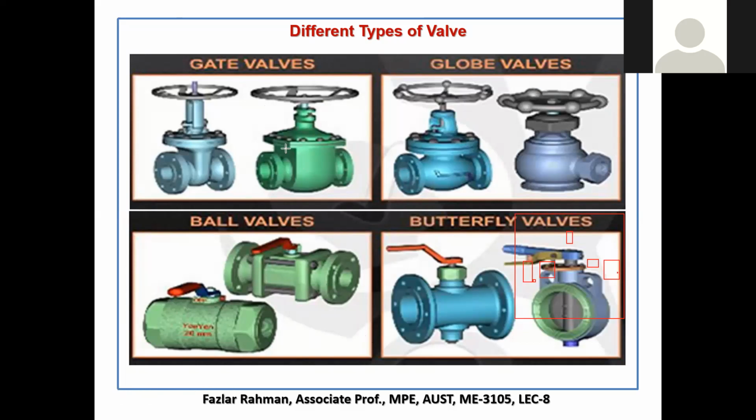Also, a densitymeter is there. So this is a type of gate valve. This is globe valve. Then you see ball valve over here. And this type of ball valve you will see sometimes if you look at your water tank area, in the pipeline they use this type of valve. Just move it 90 degrees, the valve will open and close.